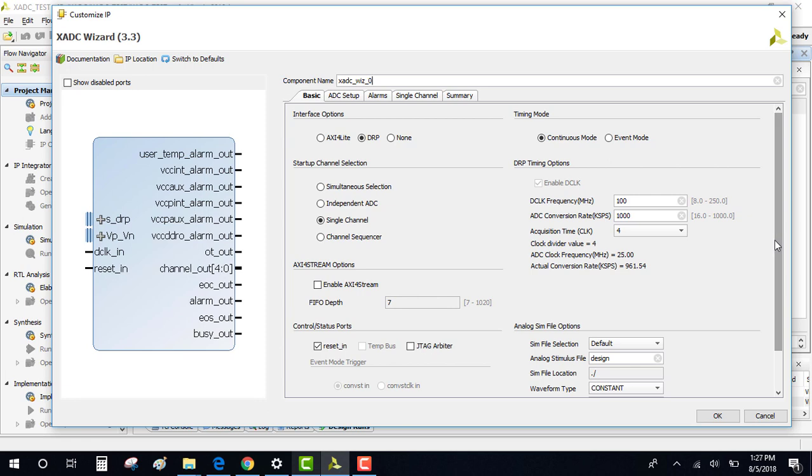All right, so the functional overview, or we can say the functionality of the IP, is basically that the XADC wizard is available in the Vivado IP catalog. It instantiates an XADC block configured to your requirements. Using the wizard, you can explicitly configure the XADC to operate in the desired mode. The XADC wizard allows you to select channels, enable alarms, and set the alarm limits.